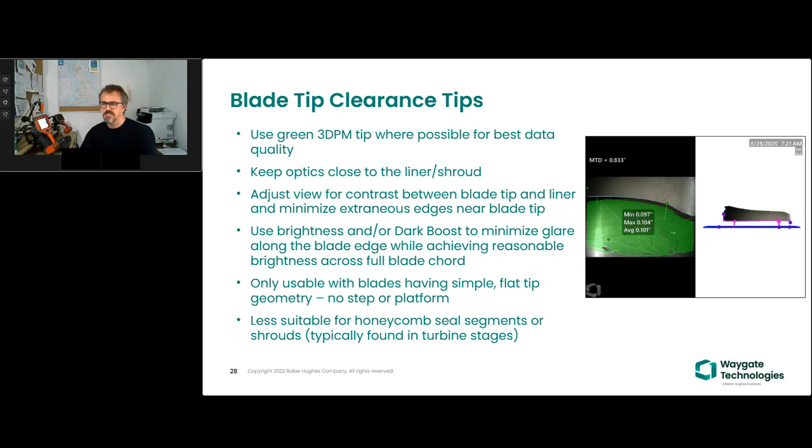It's usually a step or an inspection that's taken place at various points through the life cycle of an engine. It's usually not instructed in the aircraft maintenance manual, but perhaps during pre and post lease of engine inspections, or post an event in flight, for instance, heavy landing or engine surges, where there is a sudden shift in the axial displacement of shafts that can result in heavy wear and rub on the blades. So checking the condition of these clearances is something that can happen.